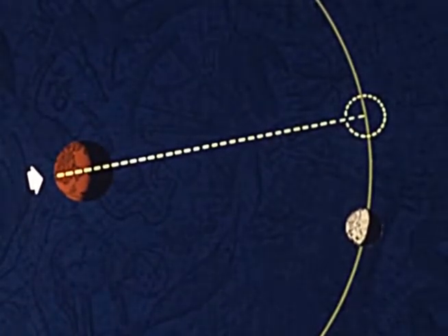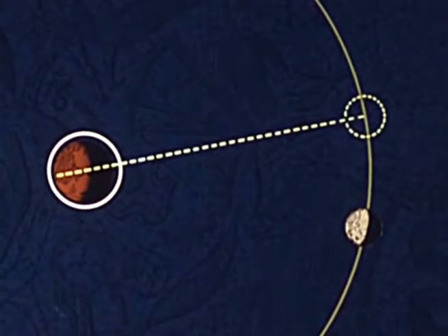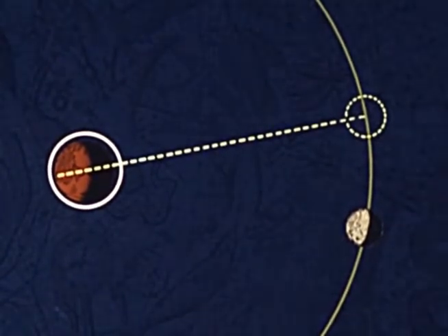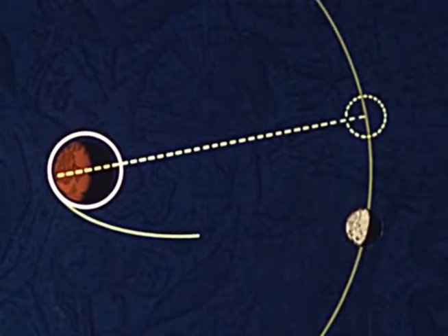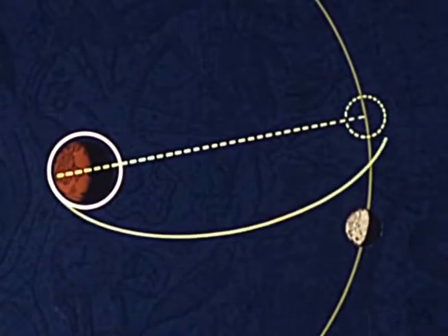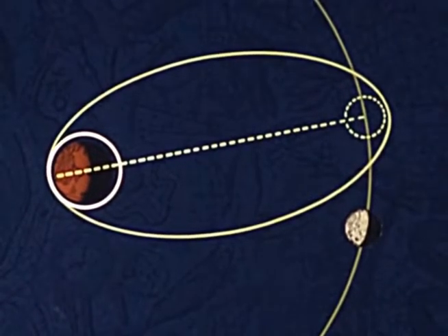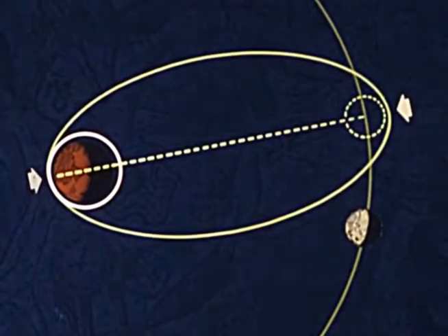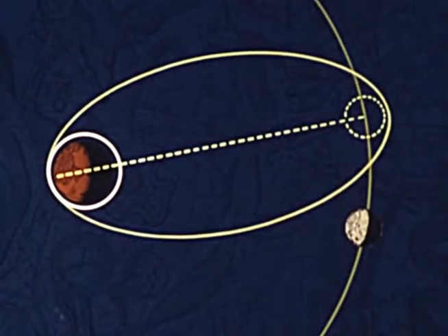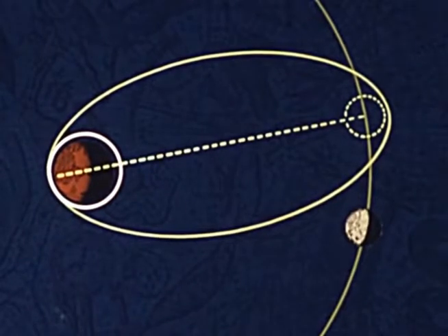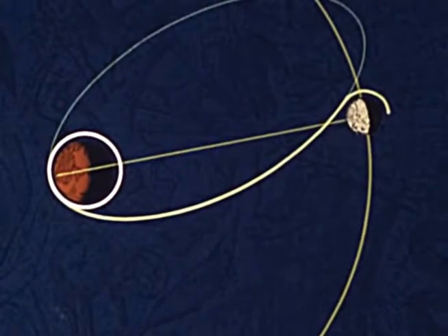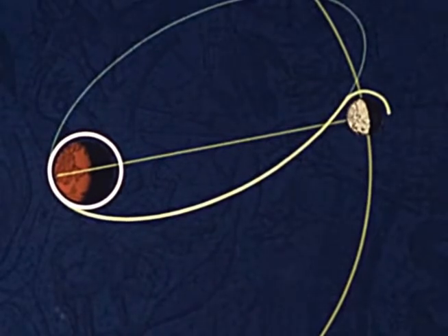The space vehicle will be placed in a parking orbit around the Earth so that required systems checks may be accomplished. The injection burn or firing of the rocket engines to place the space vehicle on its translunar trajectory will be accomplished on one of the first 3 orbits. The injection would place the spacecraft in an elliptical orbit with perigee at the antipode and apogee near the moon, provided the orbit were not affected by lunar gravity. However, the lunar gravity will perturb the orbit, so it is necessary to lead the moon by a few degrees. This means the injection burn must actually occur a few degrees after passing the antipode.